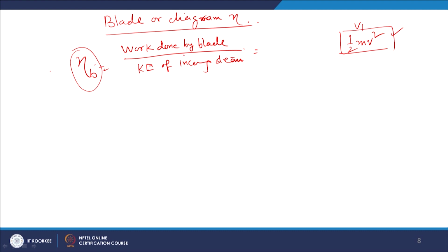In ideal condition, what should happen? It should happen something like this: steam is entering the turbine with certain velocity and there is no output velocity. Still, whether water or steam we are getting outside, then it is 100% efficiency. But practically it is not possible. Steam will leave the steam turbine with certain velocity, and this outgoing velocity will reduce the blade efficiency.